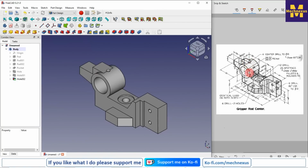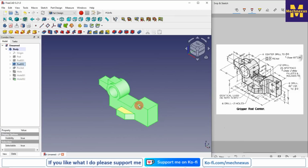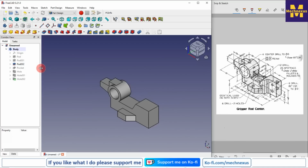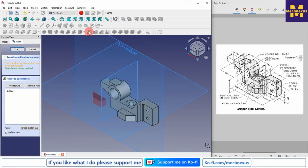Now we will move to the next tool. Our next feature is a mirror feature, so we can see that identical lugs on both the side. So we will press the space bar, and we will find out the pad. So we will, if we click on the pad 01, so we do not see this pad. If we click on the pad 02 and press the space bar, so we will mirror it on the other side.